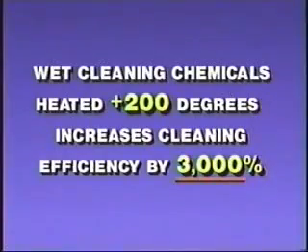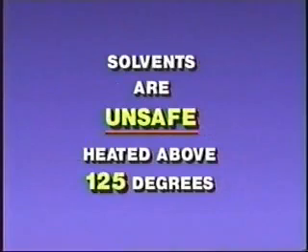When using wet cleaning chemicals, heating up to 200 degrees will increase cleaning efficiency 3,000%. That's correct, a 3,000% increase in cleaning efficiency. Solvents, however, should not be heated above 125 degrees for safety. Working at this temperature is safe and will ensure maximum cleaning results.